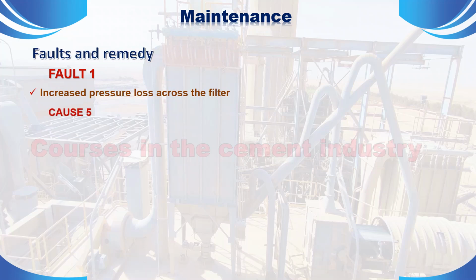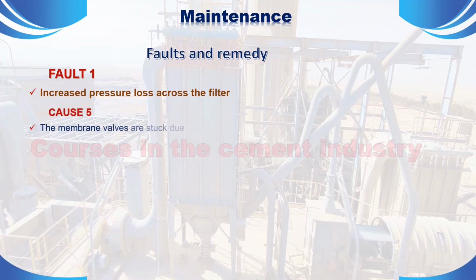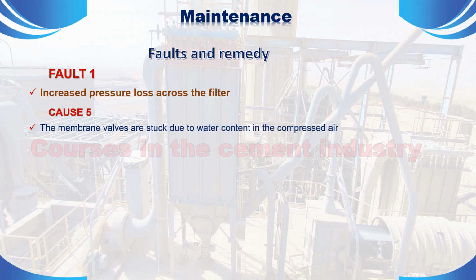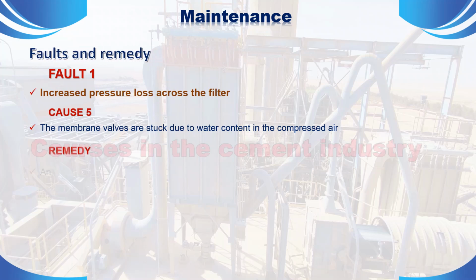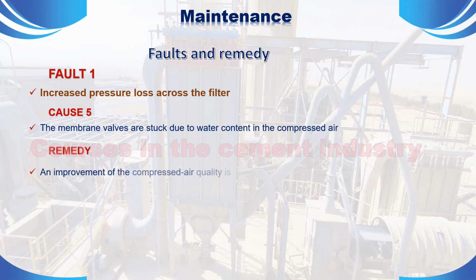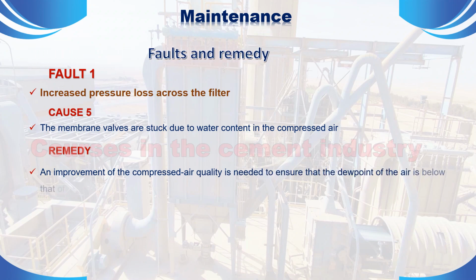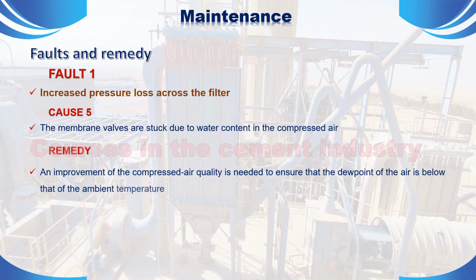Cause 5. The membrane valves are stuck due to water content in the compressed air. Remedy. An improvement of the compressed air quality is needed to ensure that the dew point of the air is below that of the ambient temperature.